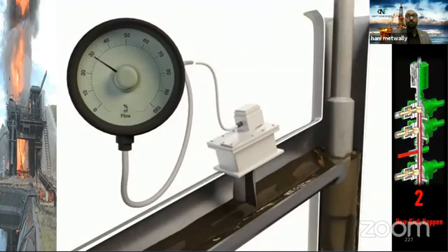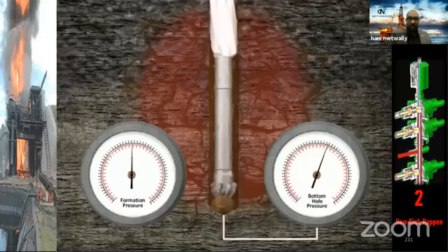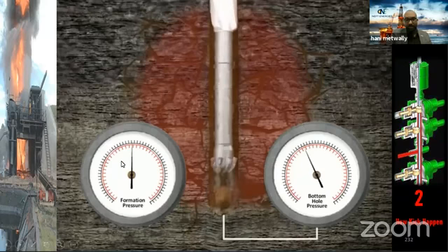As you have loss of circulation, you will lose part of your fluid through the formation. So the return will be less than normal. We decrease, we lost our return. What will happen? Yes, the bottom hole pressure is still over the formation, but by the time you will lose the bottom hole pressure. In this case, you will get influx.